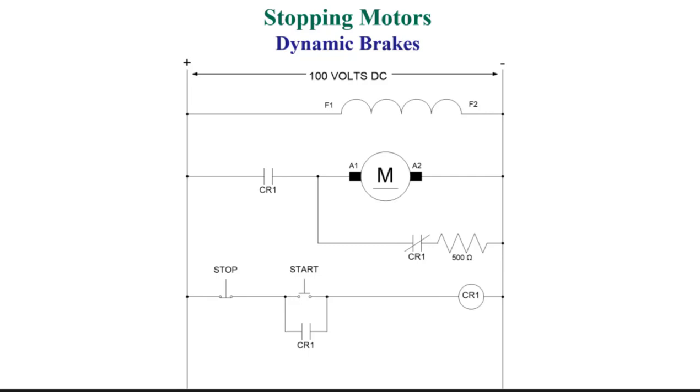And I turn those on, and that extra current that has to be delivered by the alternator flows through the alternator, which is a generator, and that means there's more counter torque. You're going to evidence that by hearing the engine speed drop down a little bit, because it's harder now for the internal combustion engine to rotate when that counter torque being created by the generator is pulling it down. So we're going to use that in this case.